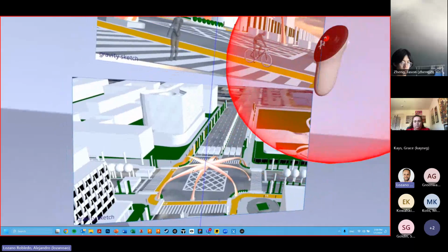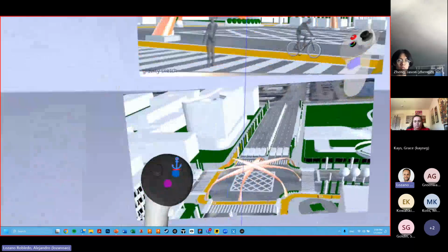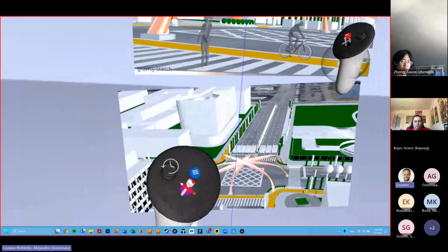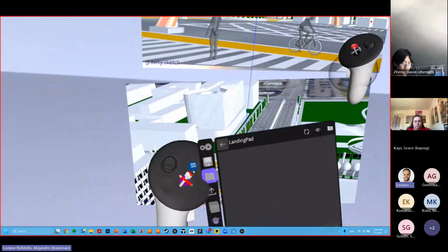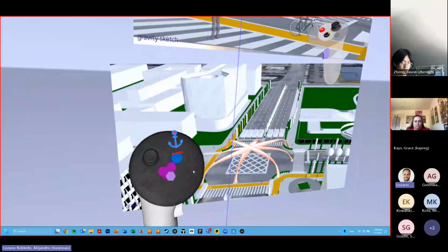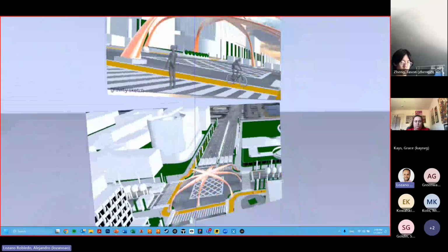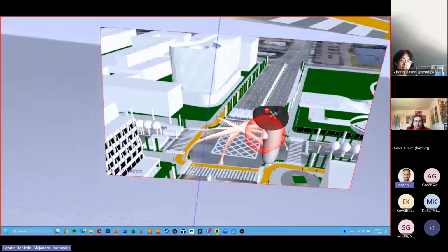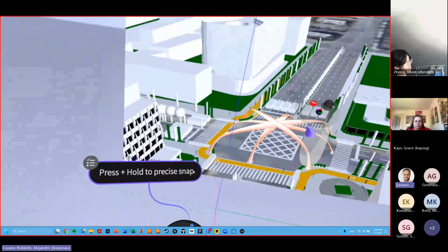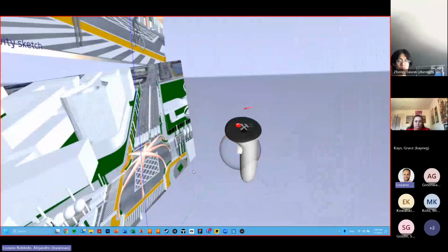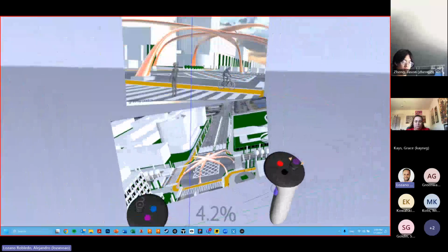So what you do is you select the images. And as you can see, my left controller now has an anchor button. Before it didn't have it, right? This is my settings if I press it. But if I'm selecting something, it has an anchor. If I press on it, now it's locked to the space. Also, if you bring it close to your center, to your mirror plane, it snaps to the mirror plane and you can have a very accurate image. So that's a 2D image.